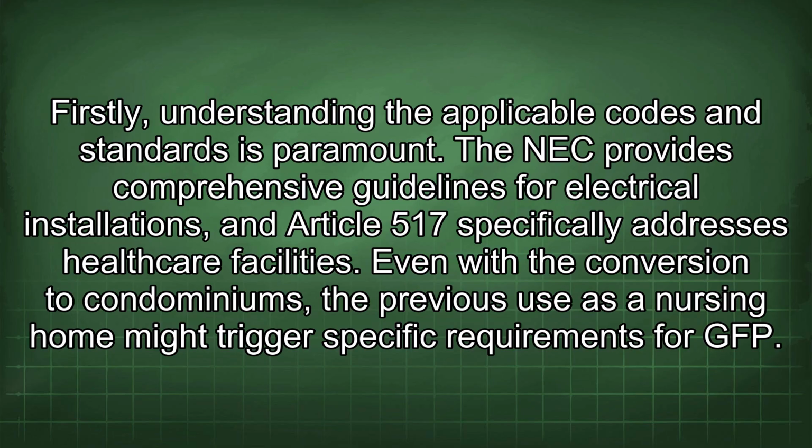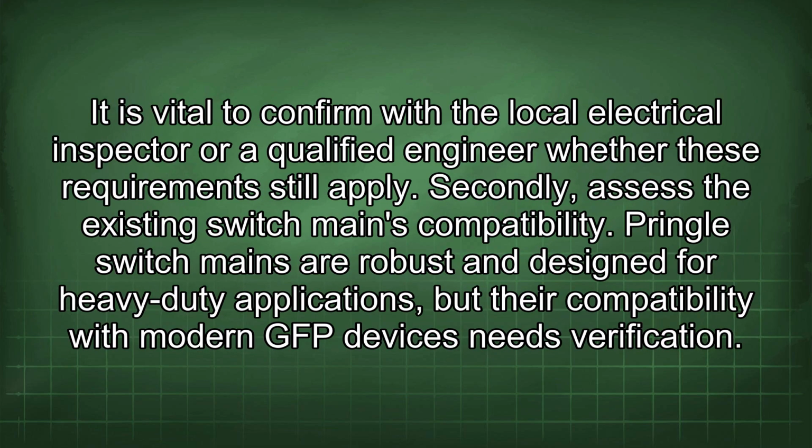Firstly, understanding the applicable codes and standards is paramount. The NEC provides comprehensive guidelines for electrical installations, and Article 517 specifically addresses healthcare facilities. Even with the conversion to condominiums, the previous use as a nursing home might trigger specific requirements for GFP. It is vital to confirm with the local electrical inspector or a qualified engineer whether these requirements still apply.